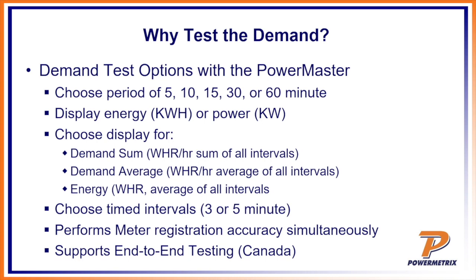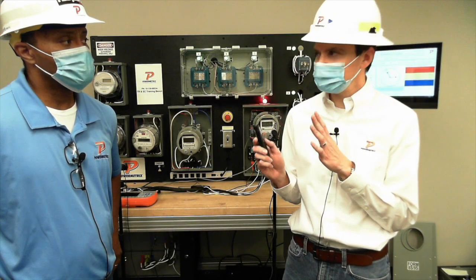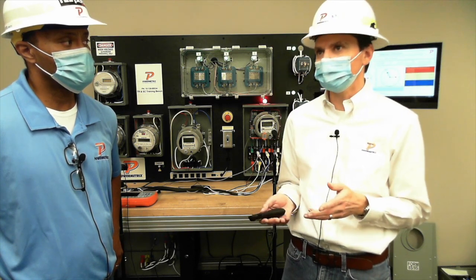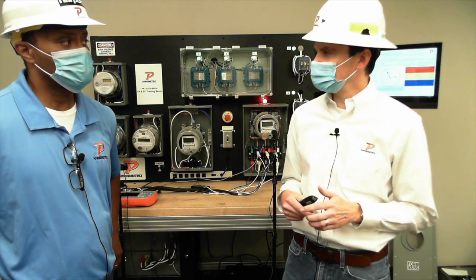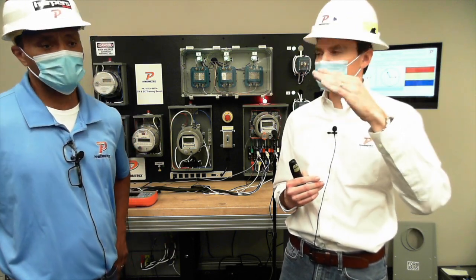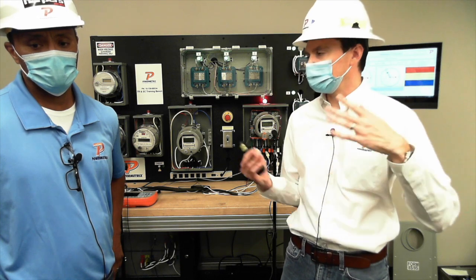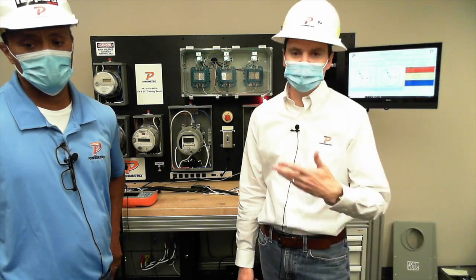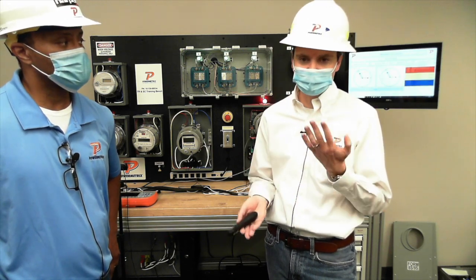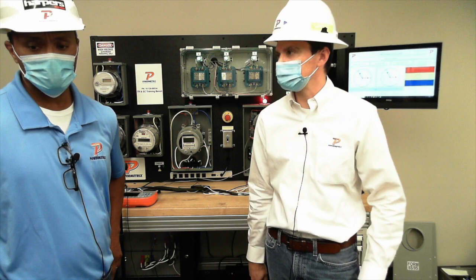It also supports end-to-end testing, which is a feature mostly used for our customers in Canada, which they call synchronization to clock. So you can synchronize it to the 5-minute increment on the PowerMaster. For example, if I started the test at 10:01, it wouldn't start accumulating until 10:05, and then it goes on to 10:10, 10:15, 10:20, and so forth. It's similar to the way the MV90 worked. That's how they were trying to match up with the MV90 and its end-to-end testing. They came up with this solution.